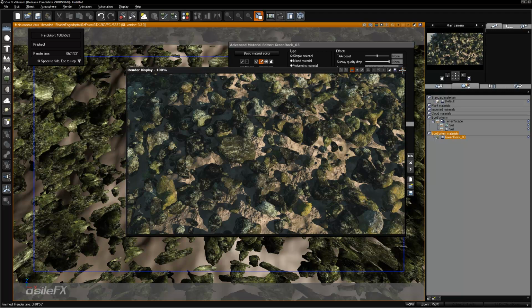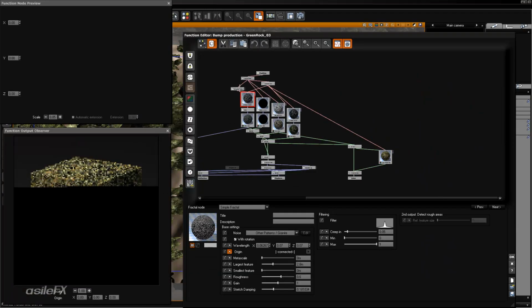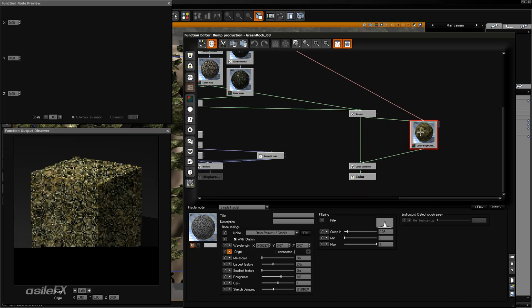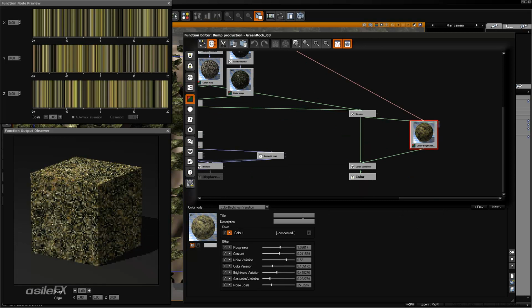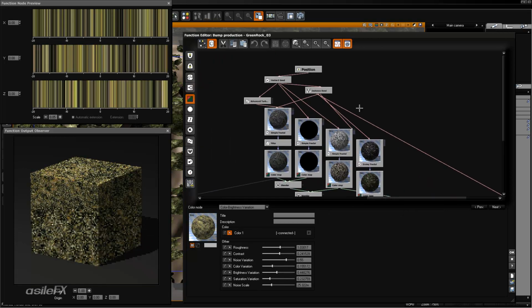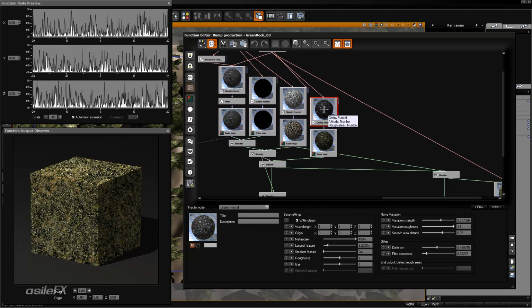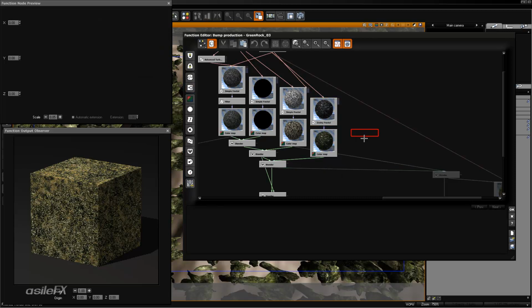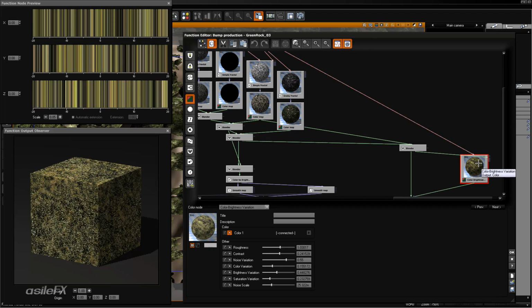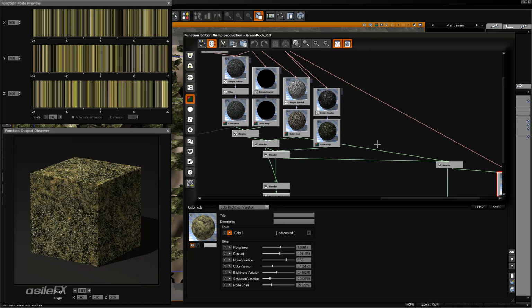And these work best if we take a look at how I set this up. I'm using a color brightness variation with the position connected to the instance seed, and a couple other fractals connected to that. Pretty much anything that has a metascale turned on is going to give the best result, because it's allowed to have a more extreme value for dark and light areas. So grainy fractals work really well. The color brightness variations, all the variations have the grainy fractal basically built into it. And of course you can use terrain fractals and anything like that too.